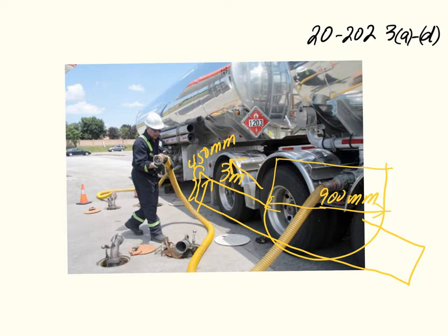And so right below that outlet, this is all a Zone 2 location, and that's either way here, Zone 2 and upwards, again to that sphere of 900 millimeters, and down is all a Zone 2 location when we're bottom loading.